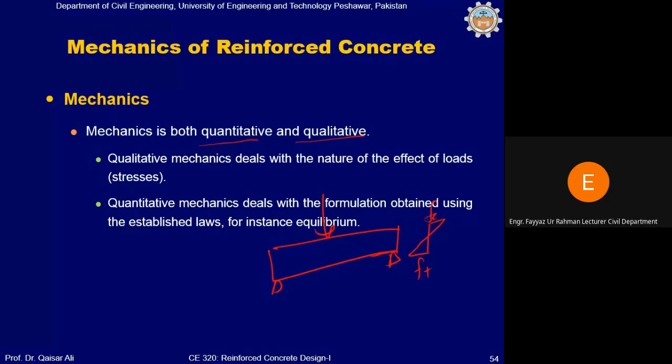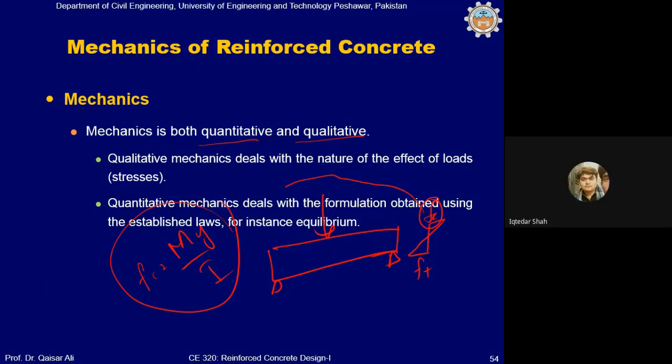Qualitatively you know that there will be compressive stresses in the top and tensile stresses in the bottom. Now how to calculate these stresses? For this you need quantitative mechanics, which you have already studied. How to calculate these stresses from this equation, My divided by I. This equation is basically based on quantitative mechanics. Is it clear now? Yes, sir.